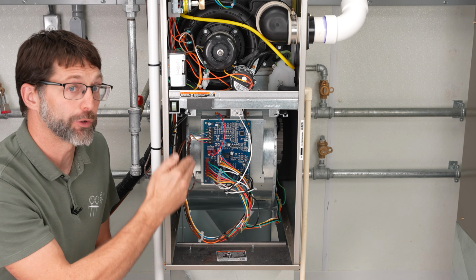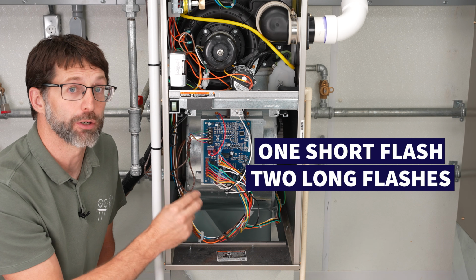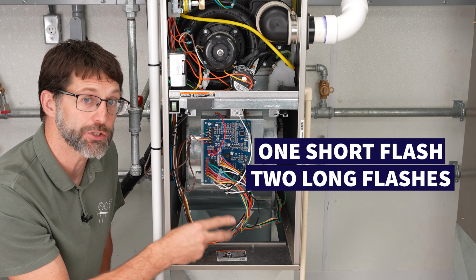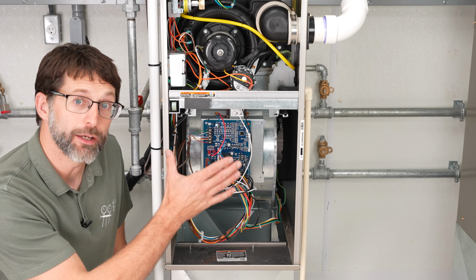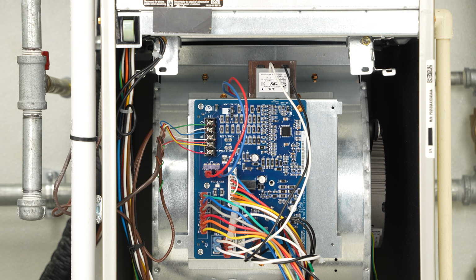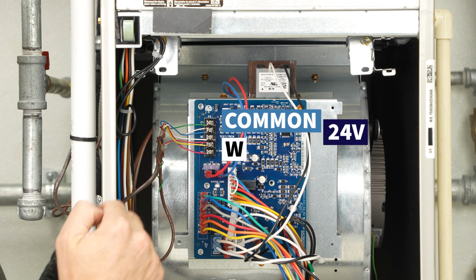So your first light is going to be a short flash, and your second light is going to be longer flashes, indicating a number 12 error code. So we're going to have 1 short flash, 2 long flashes. Now after that blower motor stops running, after 90 seconds, if you have a 24 volt signal between W and common, that means that the sequence of operation is going to turn on.